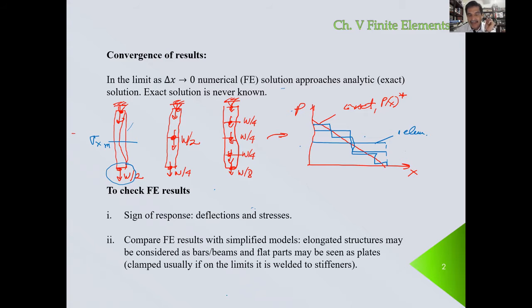They had a mast and they were having some very high vibratory response, which did not allow the electronics to work correctly. In those cases, you can immediately see that this structure could, in a very simplified way, be analyzed as a beam and bar, which is something that we can solve using solid mechanics.